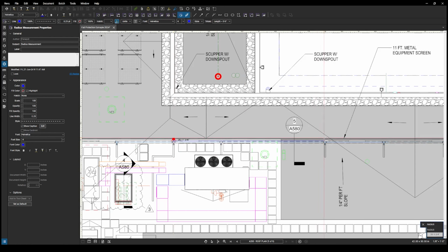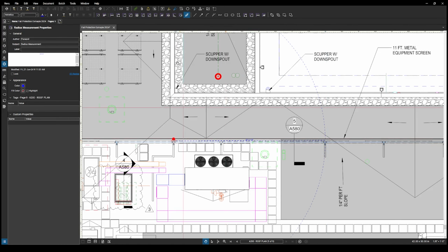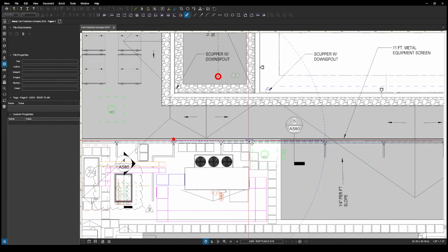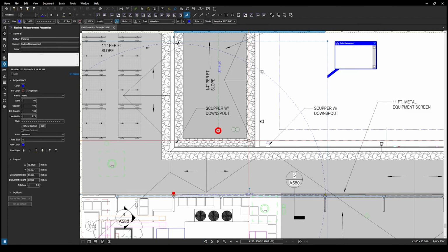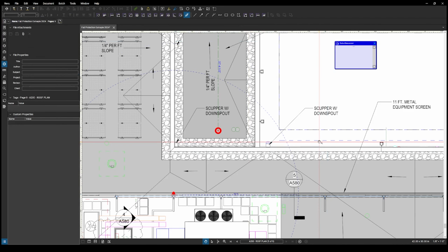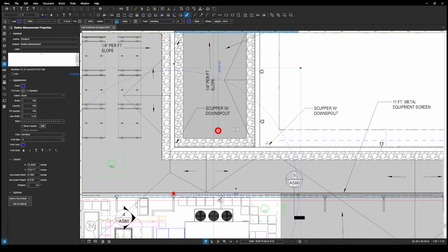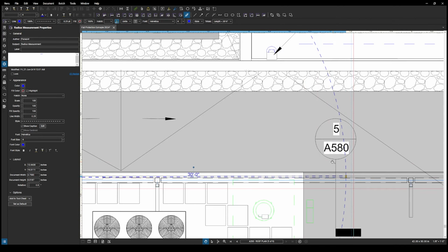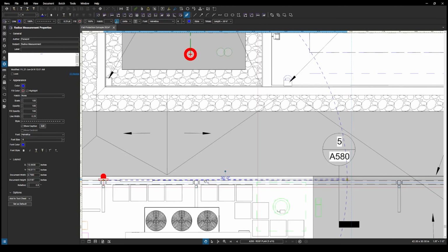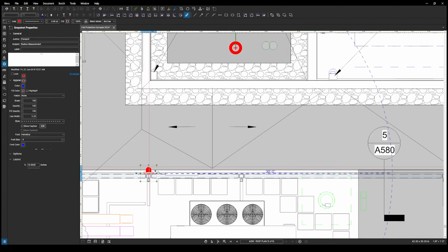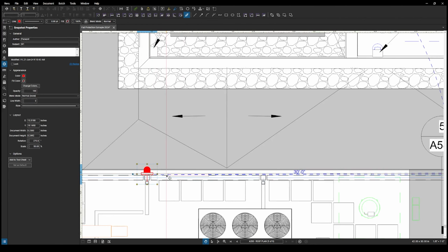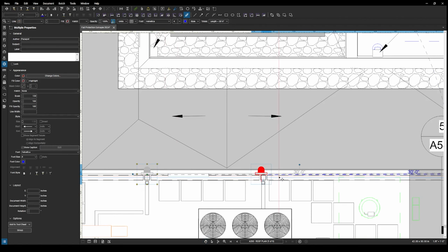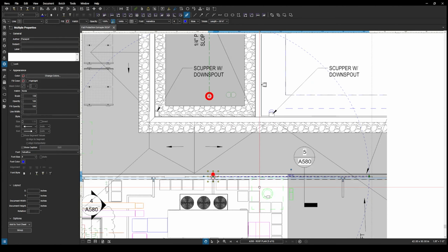So the best case scenario for a wall anchor at a screen wall is that we use either the horizontal beam or the girder I-beam. So not every girder though is meant to take any load, let alone even something light. So at this point, we're just going to be ignoring those for now, and we're going to be placing anchors at the vertical points. So we've got one anchor there, and we're just going to repeat basically what this drawing has for most of these situations. I'm going to place another one there, another one here,